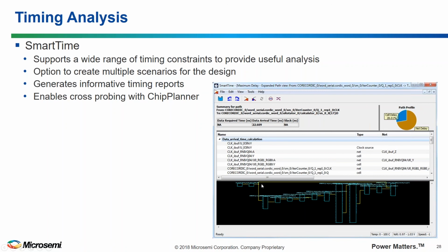Once you've completed layout, you move on to the timing analysis step. And we have a static timing analysis tool called SmartTime. SmartTime supports a wide range of timing constraints. You have an option to create multiple scenarios, so you could use different timing constraints for different operating conditions if you wanted to.